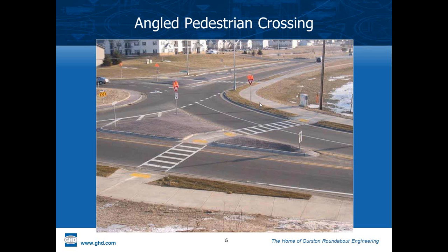the walking distances. The splitter island should be wide enough to provide for a refuge, and in the roundabout guides, it's generally the length of a bicycle, roughly 6 to 8 feet. You can imagine a bicycle with a trailer or a child's stroller attachment to the rear of the bicycle that you could need upwards of 10 feet of crossing area as a refuge.